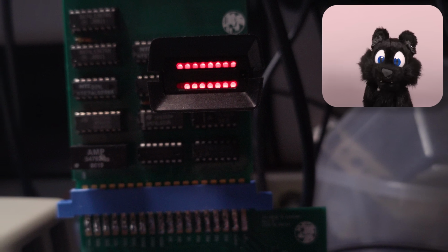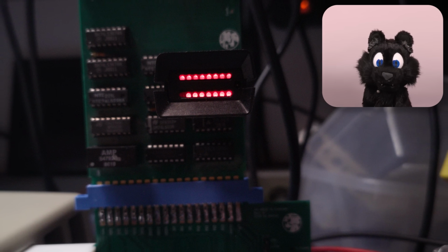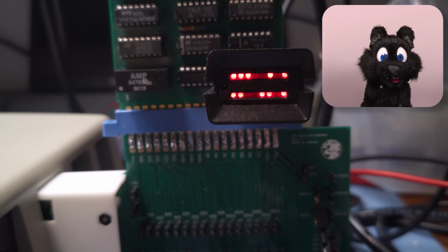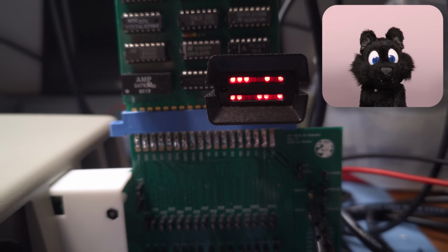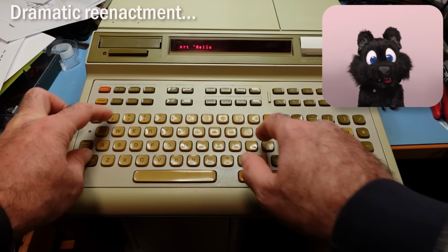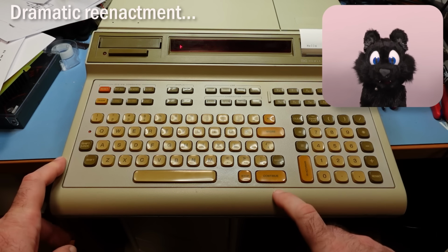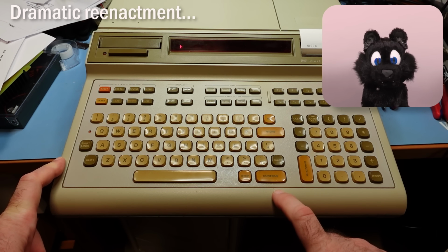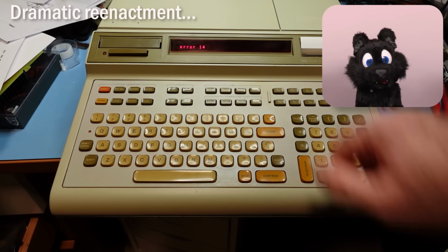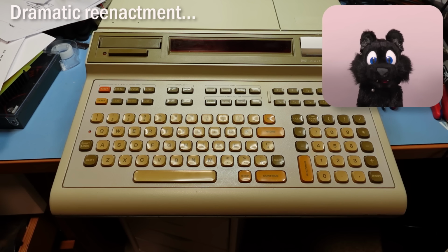This is when I realized that the source of the problem might not have been the RAM after all. The error 14 issue goes away as soon as I remove the I/O option ROM card. Yikes! Can it be that the old ROM chips are having thermal issues? It's repeatable. Power on a new day, it works. And once it stops working and gives the error 14, it will do so until the I/O ROM is removed. Then it works fine again.